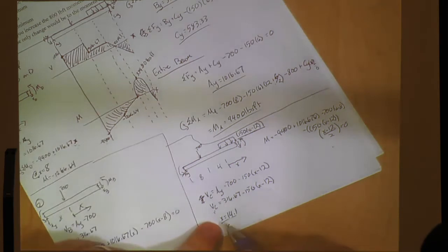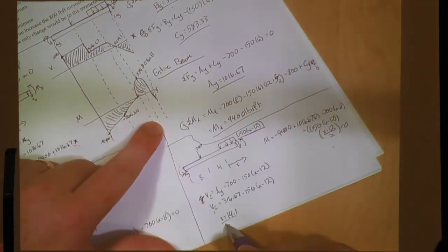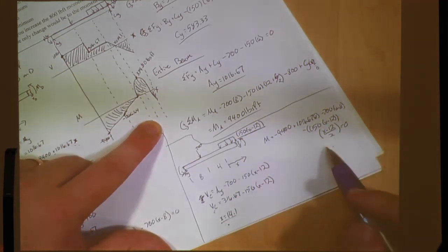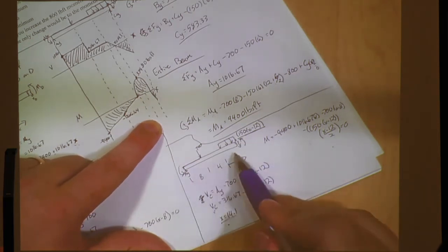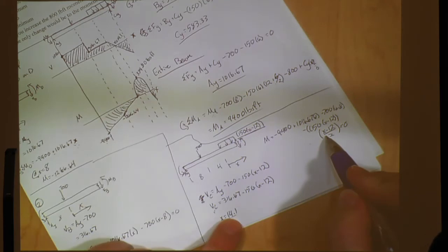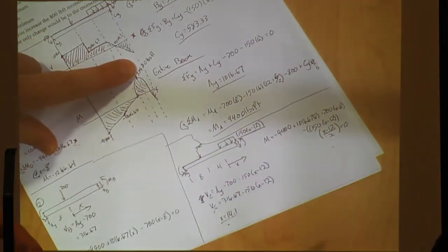Once we solve for that exact point, we draw a dotted line down through our moment graph. That's going to be the peak of the arc of the moment curve. We solve for the moment equation over here by doing the section method. We plug the 14.1, the distance, into the moment equation to get the number for the max moment. Make sense?